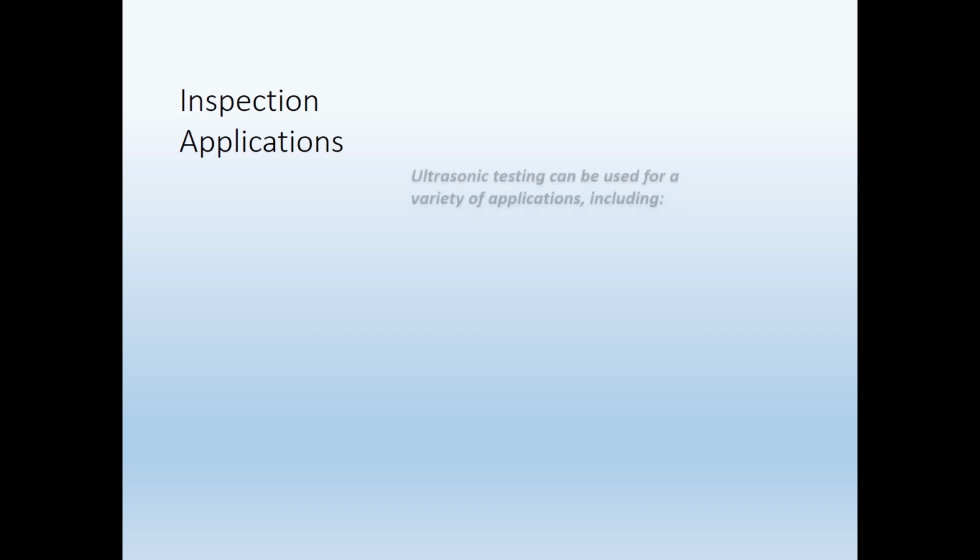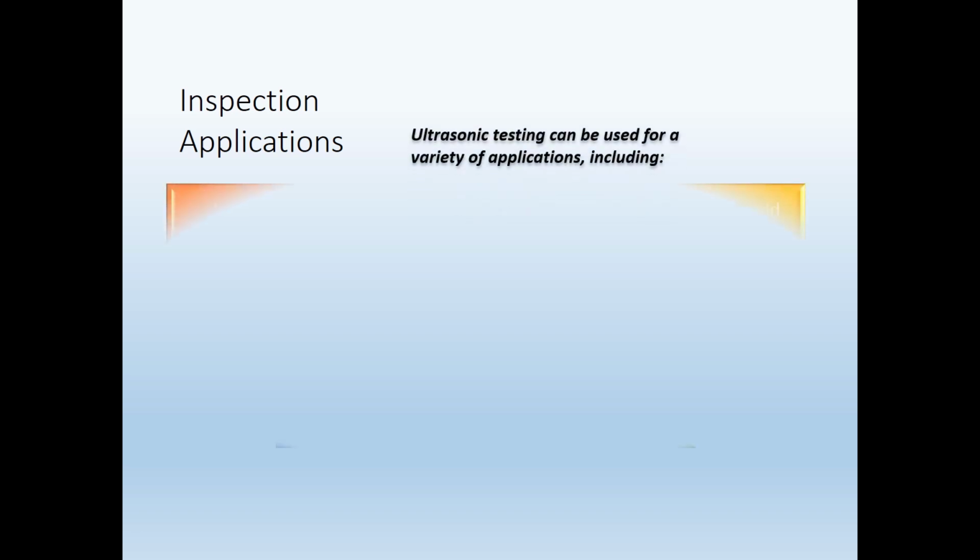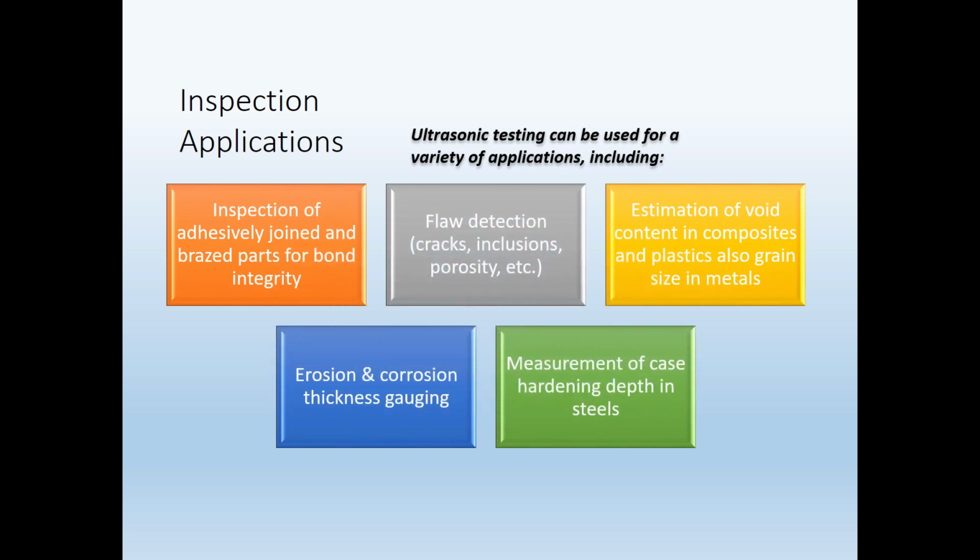Now I will talk about application. Ultrasonic testing can be used for a variety of applications including flaw detection, measurement of case hardening depth, assessment of corrosion and erosion, thickness gauging, and estimation of fault size.